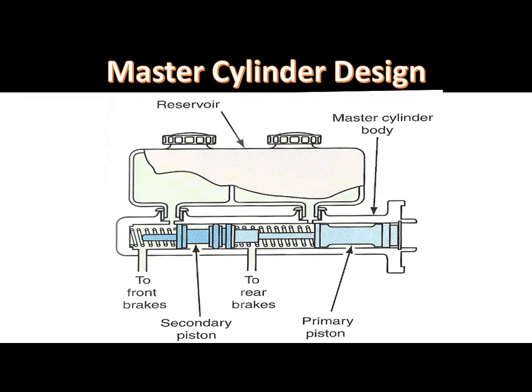If the brakes are applied repeatedly, the brake fluid may become very hot. Under this condition, the fluid expands and some fluid flows back through the vent ports when the brakes are released. The vent ports prevent excessive pressure buildup in the brake system.